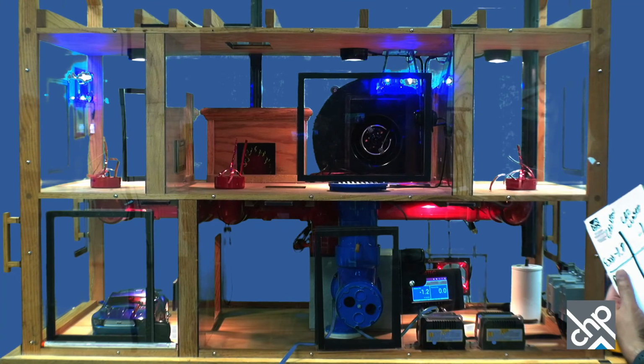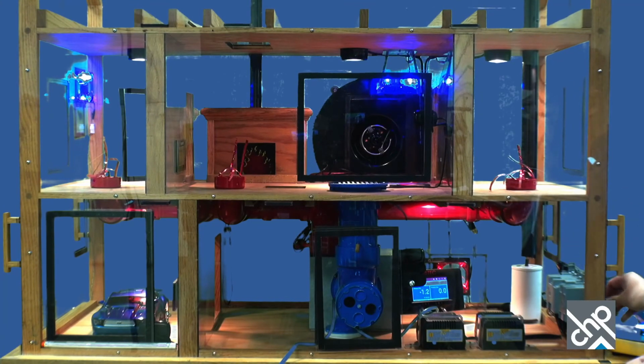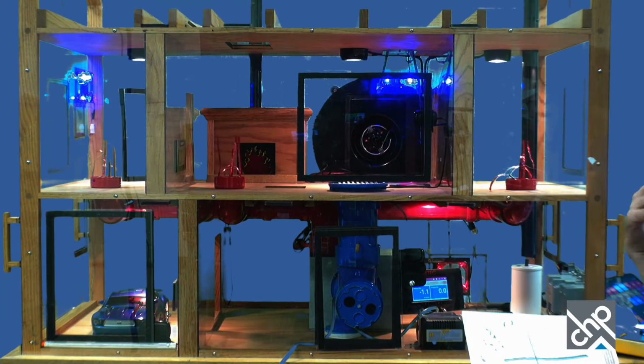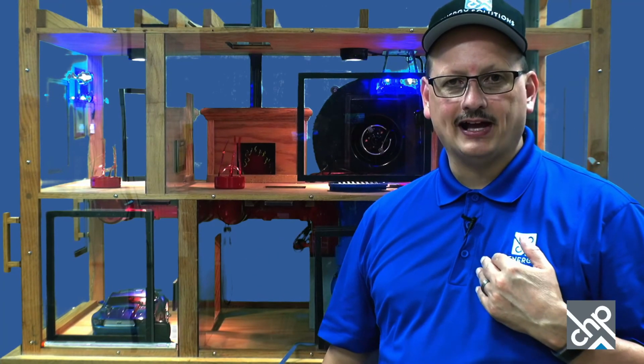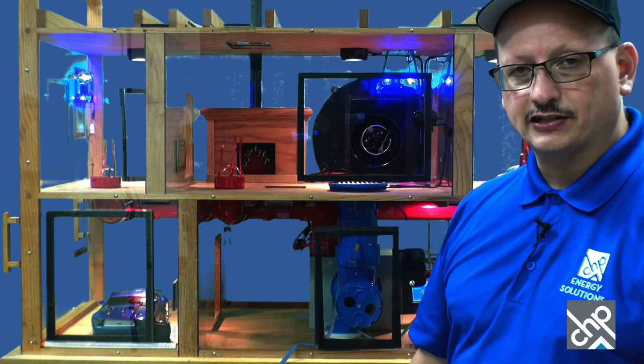Now we want to turn on the air handler fan. Remember that? So we turn on the air handler fan, and then you're going to check each one of those doors. And like I say, ones that just have supplies behind them should be blowing smoke back into the room, and those doors will stay closed. The ones that have exhaust and supplies may go either way, depending on which one's stronger.